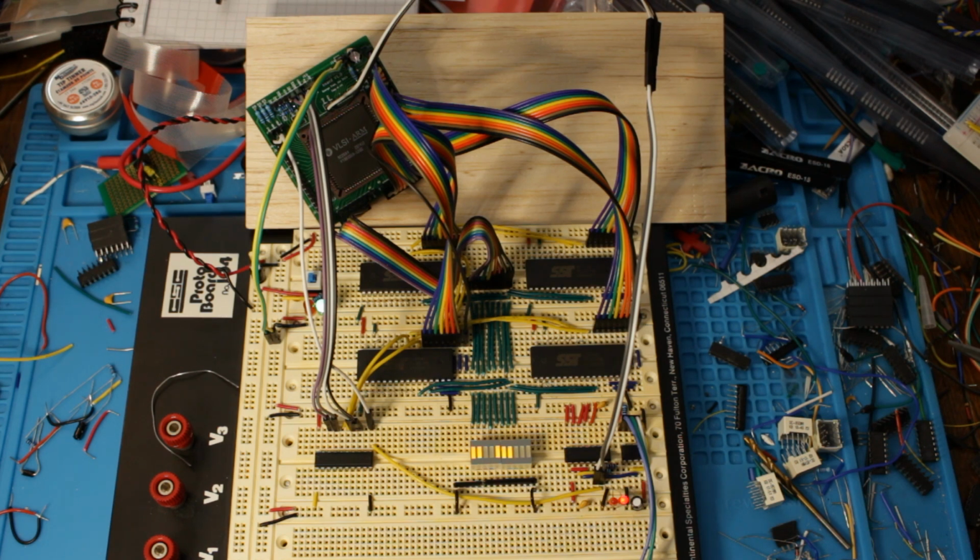So I'm going to have to think about what to do in the next video. I could take these ROMs out and program something much more elaborate and interesting into them. I've been thinking about making a debug port. This would essentially be something which captures writes to a certain memory location, or maybe just capture all writes, and I could indicate on a series of 32 LEDs at the bottom here what the last value written was, or something like that.